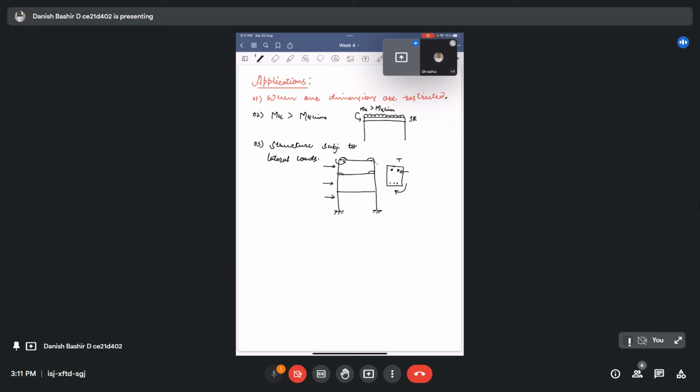Second point, I said that when the loading on our structure increases to such an amount that the existing beams, which would have been singly reinforced sections, have moments that cross the limiting moment resistance of that beam, so that they are no longer able to resist the applied moments. For those cases, we shift to the doubly reinforced sections.